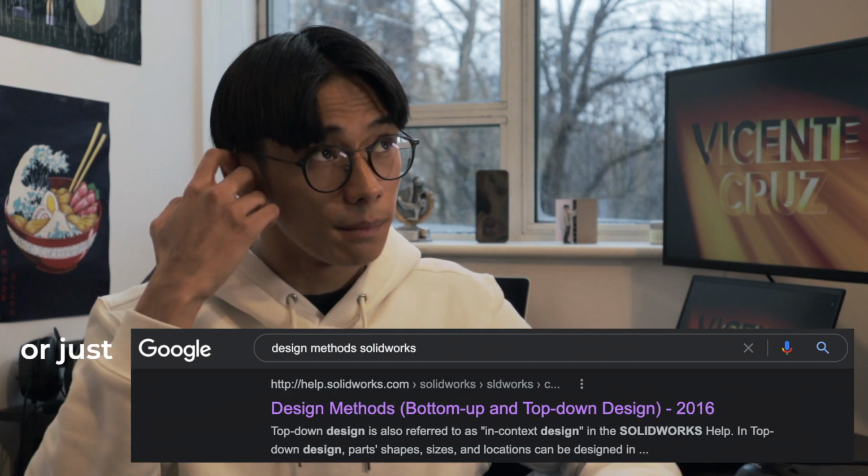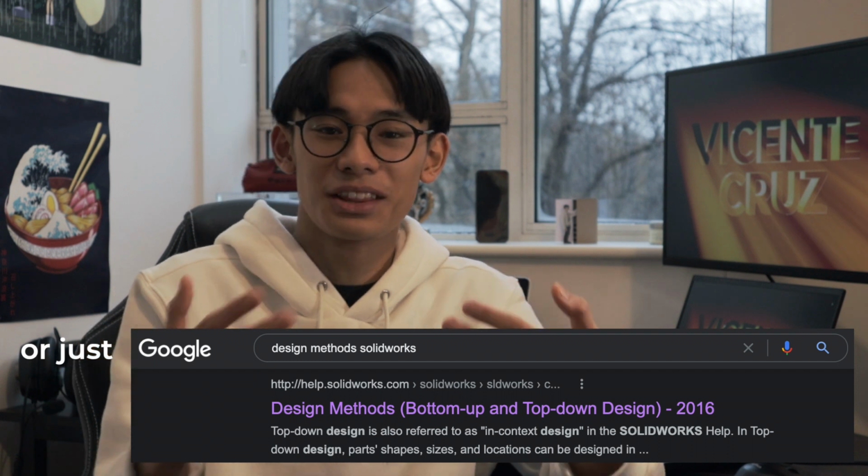One big mistake I made in designing my wardrobe was that I used a mix between a bottom-up design method and generally just freestyling it in a part file. I'll go over the differences between a bottom-up and top-down design method in a later video, but basically I created the whole product in a part file, then realized that I needed to make an assembly to create exploded views and export individual parts. This added 10 plus hours simply because I had to recreate the whole model in an assembly file.